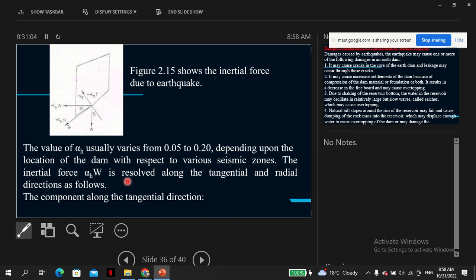If such an event has not occurred for the last 200 years, then because you design a structure to last 200 years, yourself as a designer, you will not even live to see it. So 200 years is fine. If such a magnitude of an earthquake has not occurred for the last 200 years, then you may not need to design for it, because in 200 years the building would have served its purpose and recuperated its project cost. So no need.